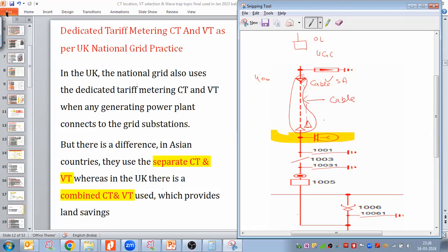Length of the cable. Then the cable comes, and first of all it connects at the sealing end. You can see this symbol is for the sealing end. Generally, the sealing end we do not indicate in the SLD, so that's why it is not indicated here. The sealing end we indicate in the layout drawing. It is like cable termination, right, sir?